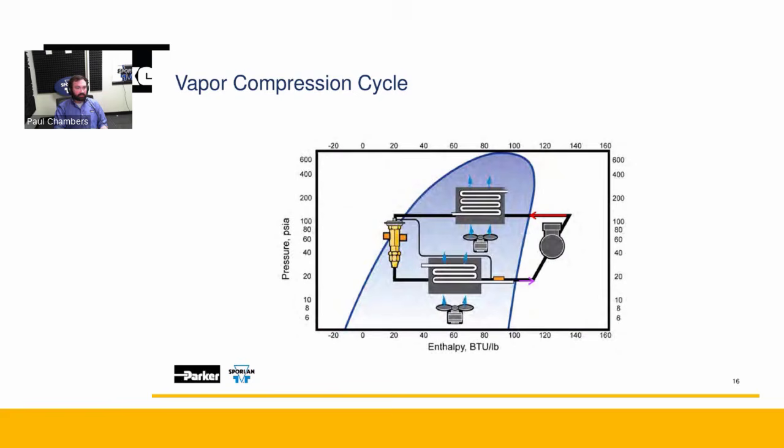We also said that the compressor adds a little bit of heat. So if I were to draw it more realistically, it makes this kind of trapezoidal shape with one at an angle. Because it comes out, we have superheat coming out of the evaporator, and then it continues to get some heat from the compressor. A few things to be aware if you see someone draw a picture like this, and those eagle-eyed viewers of you might have noticed there's some errors. One is that every line here is an entire component. The compressor is not in the middle of that line. It is the whole line.